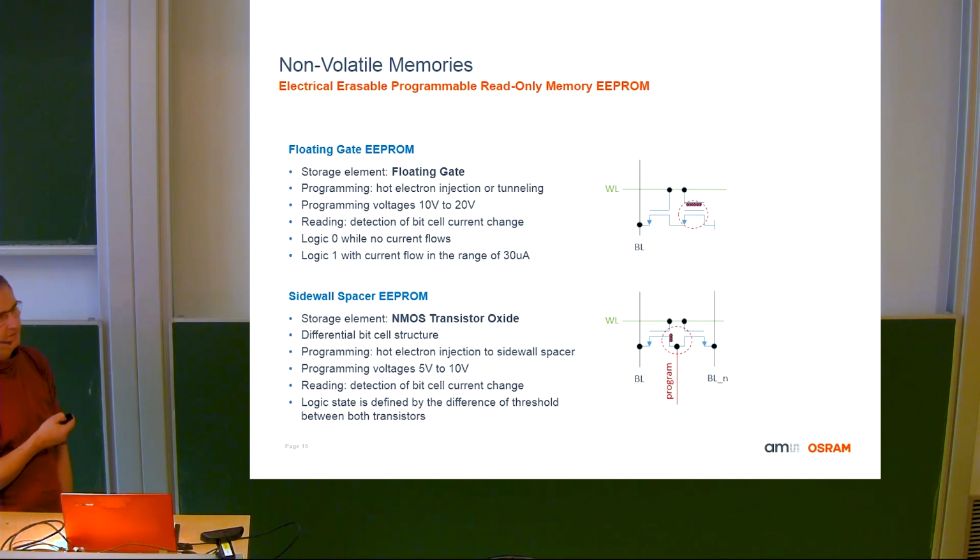So of course, if you increase this, the capacitance will decrease. What you can compensate this with is area. So you build huge poly gates and coupling plates. So by avoiding special process nodes, you increase the bit cell. Disadvantage is, of course, you end up in a few kilobits maximum range for these approaches.